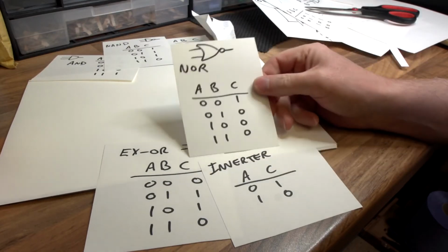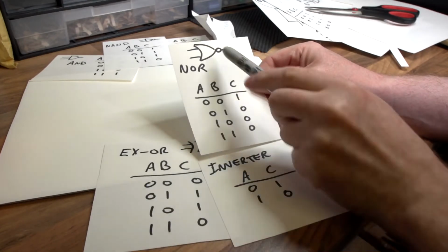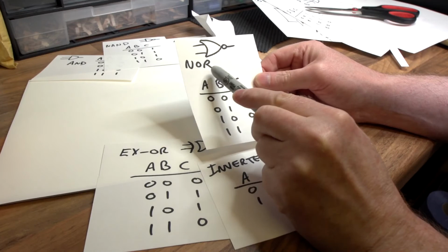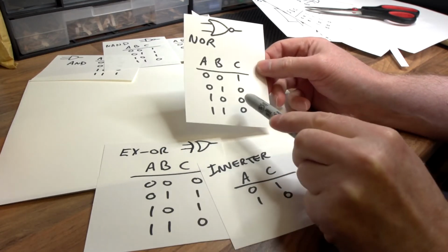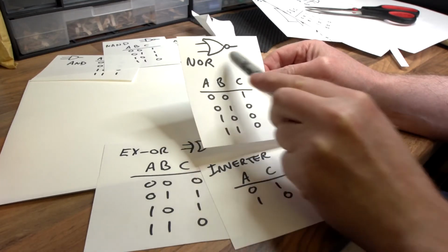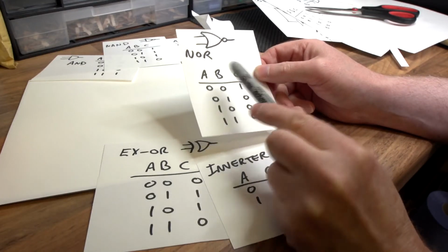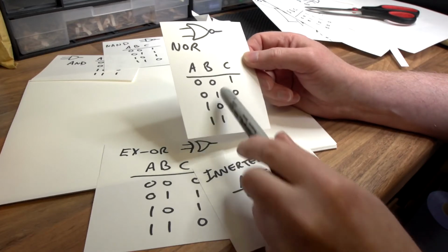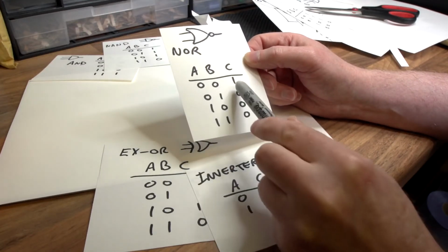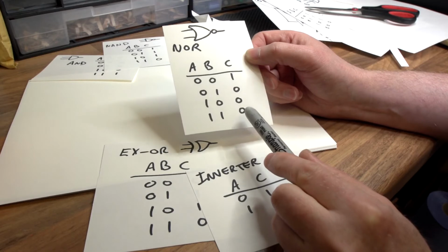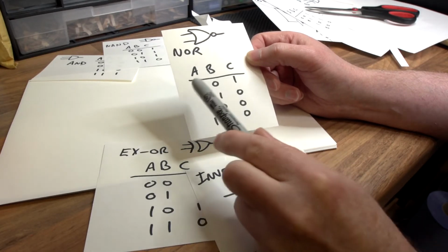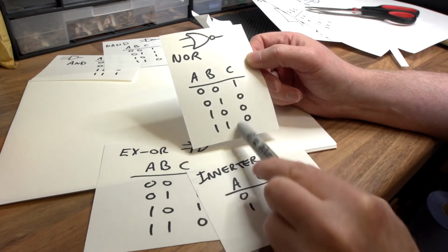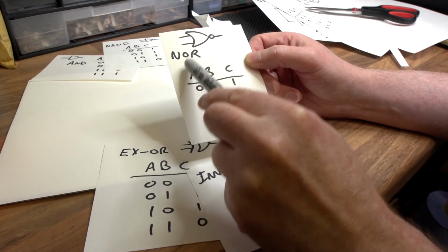So then we have the NOR gate, which uses the same principles as before, where we've got the little circle on the output, which means not OR. So whatever an OR gate would give us, we invert it because of the not symbol. So for A, B inputs and C output, this is what we would get. Normally for an OR gate, any of the inputs can be on, and that would normally give us a 1 output. So this is the inversion of that. So they're now all 0, and it's only when there's no input at all, you get a 1 output. It's the exact opposite output of what an OR gate would be, a NOR gate.